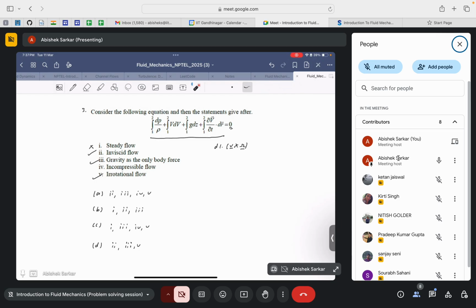But I'm saying again that for us to be able to solve for the forces that act on the fluid element with only the momentum equation, we take an assumption that the flow is incompressible. Then only we can disregard the mass conservation equation, the coupling between the mass conservation and the momentum conservation, and only deal with the momentum conservation term to solve for the expression of pressure.